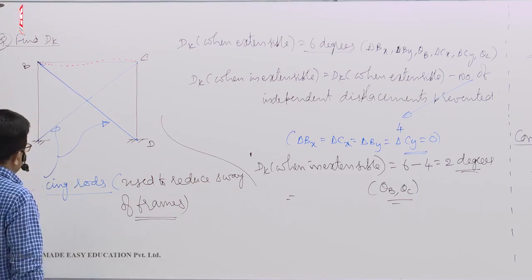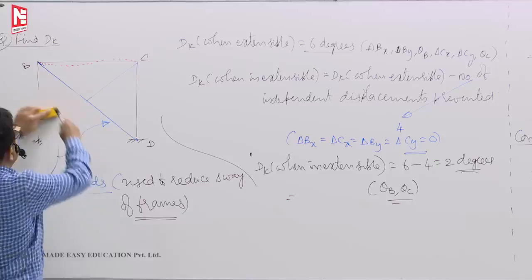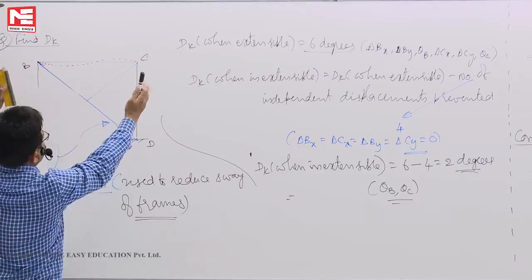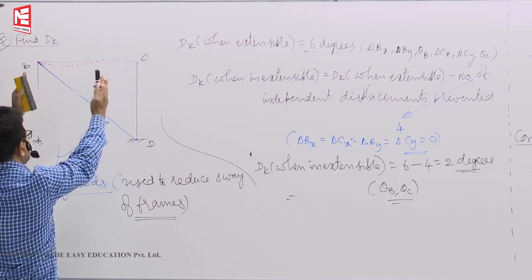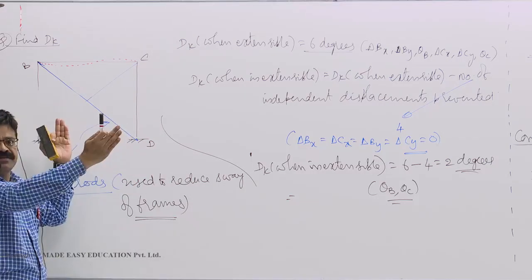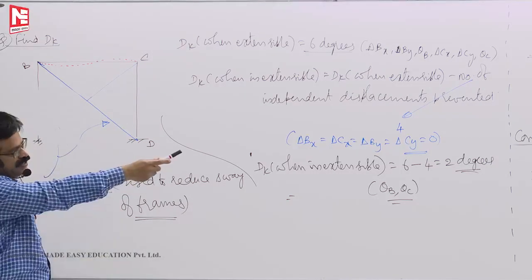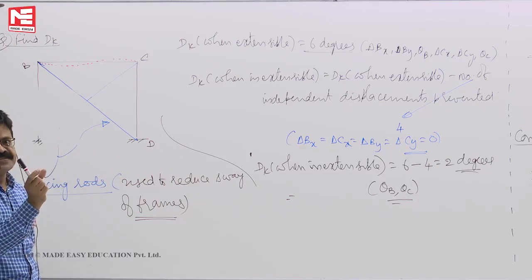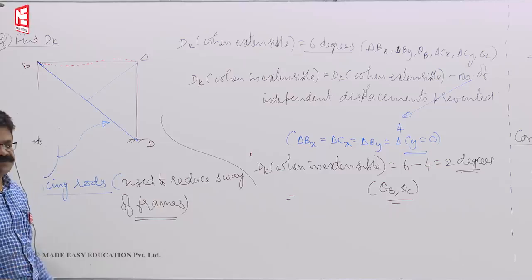Now let us see. I think about the second order displacements for this type of curve. To accommodate that, BC would have to go in or out, but they are so small, as I have explained. Delta B into theta type displacements are second order, so round them off to 0.